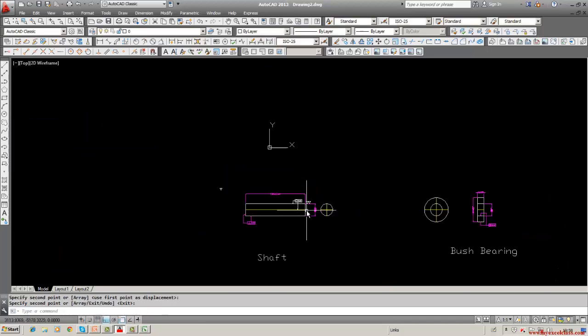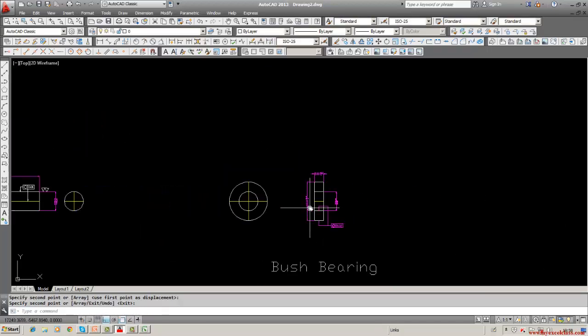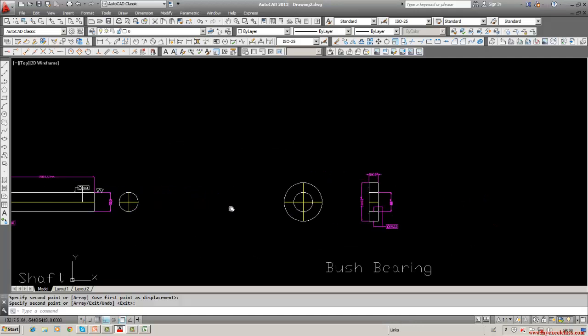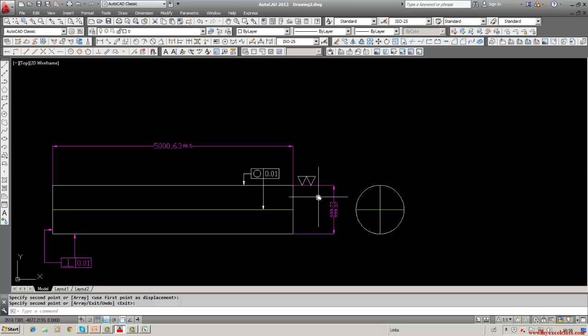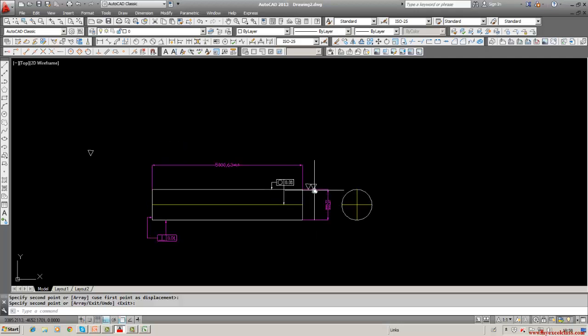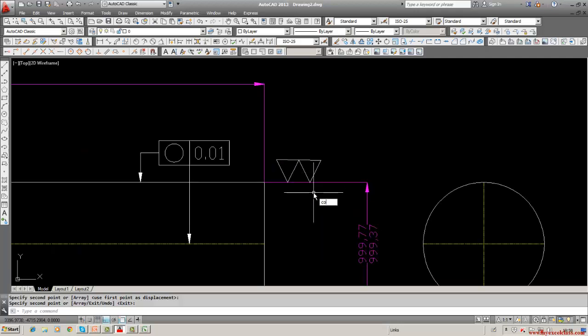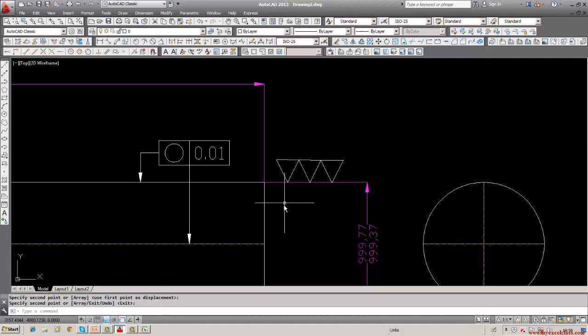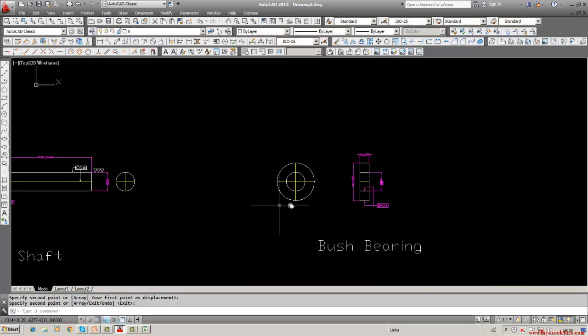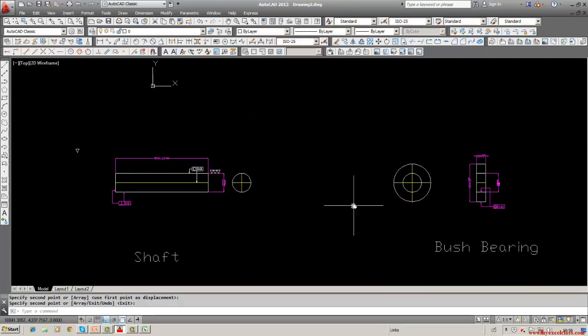And suppose you want double, we'll extend this. Like this. Okay. And if you want grinding, you can put 3. So we'll do outside, you will have finish. We will have 3 because the shaft should be ground. And then for the bore, you can copy that thing.